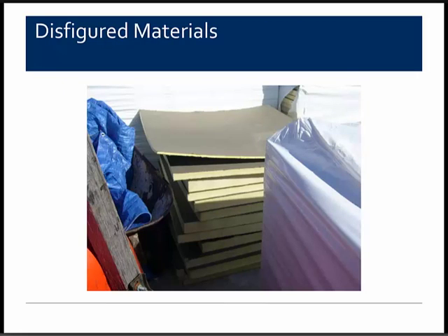And just to piggyback on the previous slides, you want to make sure that the materials are not disfigured prior to installing them. This particular picture shows an insulation board that was possibly wetted at one time and has cupped. Try getting this piece of insulation to lay flat. Is definitely going to be a chore. We would recommend not using this type of material in any kind of assembly.